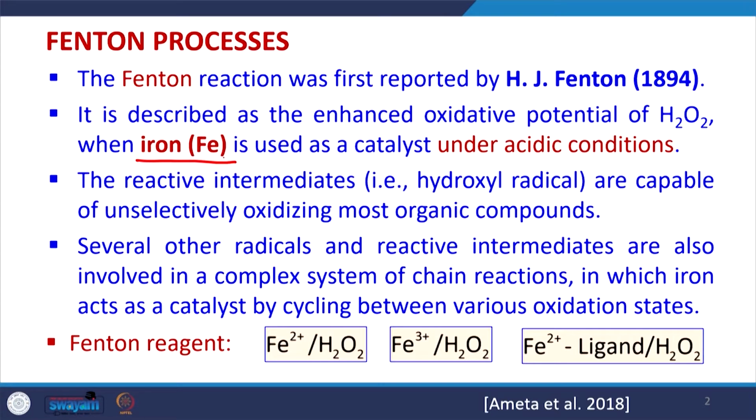Under acidic condition this iron will remain in the form of Fe2+, which is desirable. If hydrogen peroxide is added, it initiates a process where a lot of reactive intermediates such as hydroxyl radicals are produced, and they unselectively oxidize most of the organic compounds present in the water.